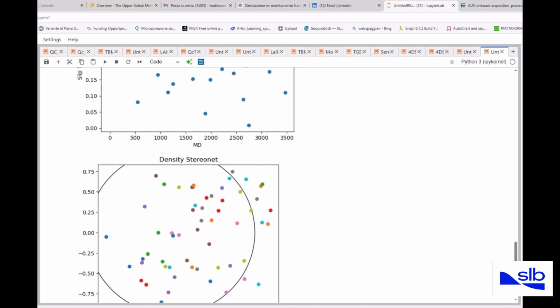We have also the perforation placements, the plot position. We use oriented perforating and MWD measurement-while-drilling tools. The face we can tell is affected by the high side of the pipe, and we use it to ensure the exposure of charges fire in a specific direction.